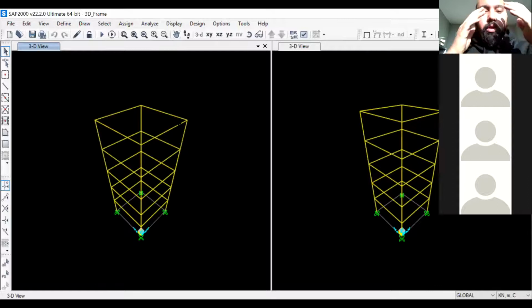That's how you see the data about the model by using the View menu and showing the labels of the joints and the elements. And you can set the views, so you can see a specific element away from the other elements and so on, or a specific joint. And yeah, you can run the model using this small arrow, a small triangle.